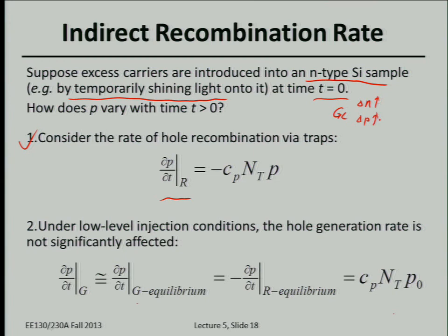Like by a very large order. So basically, right now I have a lot of excess electrons and holes, okay? But we assume low-level injection, right? Delta N is much smaller than the equilibrium state electron concentration. So basically, this part is negligible. Let's just talk about the impact of delta P we created.